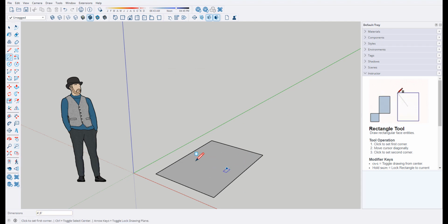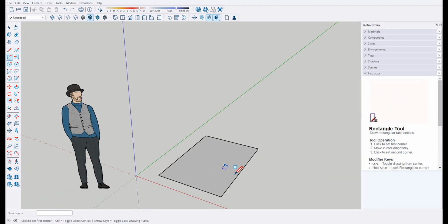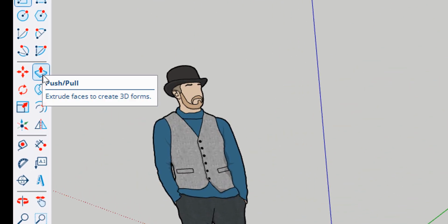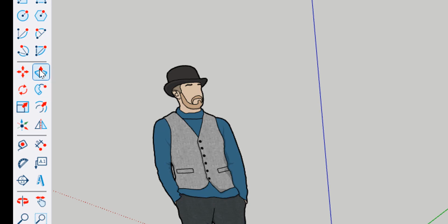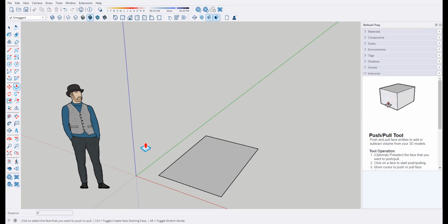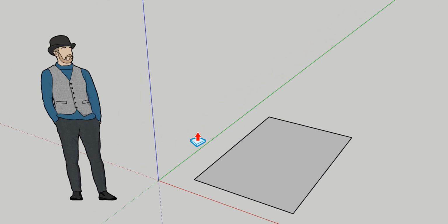So once you have the base of the shape, then you push-pull it into 3D. And we'll use this tool right here. This is the push-pull tool. So I'm going to select it. And when I move away, you can see my cursor changed to that push-pull symbol. And now notice too, it's got a little point to it, right? So I know the pointer is the top of that red arrow. Notice that when I hover over the shape, because I can push-pull this shape, I get these little blue dots. Again, another visual clue that you can do something with this. Notice when I put it over here, I don't. I actually have a can't-do symbol next to it.